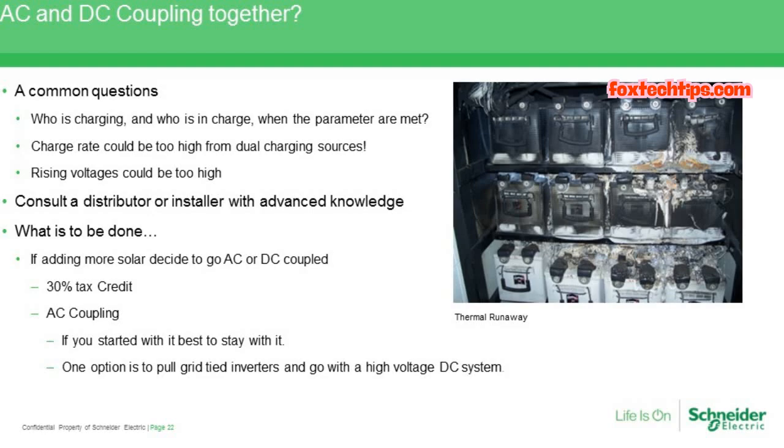That big box there on the left-hand side has the DC disconnects for the batteries as well as PV. And then down below with that AC combiner box, we can see that little rocker switch there on the right-hand side. That's the IOB kit, which keeps the input and output bypassed in case you need to work on the inverter, but still need to have the loads powered in the distribution panel going.